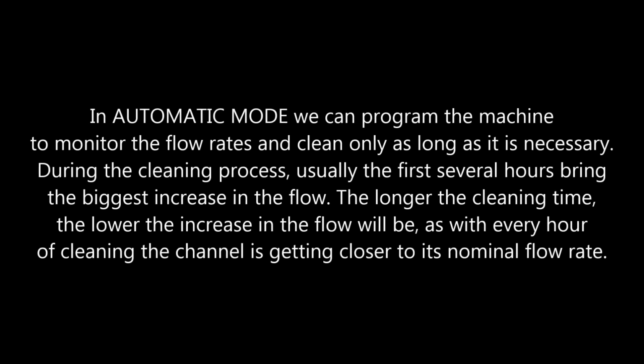Automatic mode, cleaning until stable flow results are reached. In automatic mode, we can program the machine to monitor the flow rates and clean only as long as it is necessary. During the cleaning process, usually the first several hours bring the biggest increase in the flow. The longer the cleaning time, the lower the increase in the flow will be, as with every hour of cleaning, the channel is getting closer to its nominal flow rate.